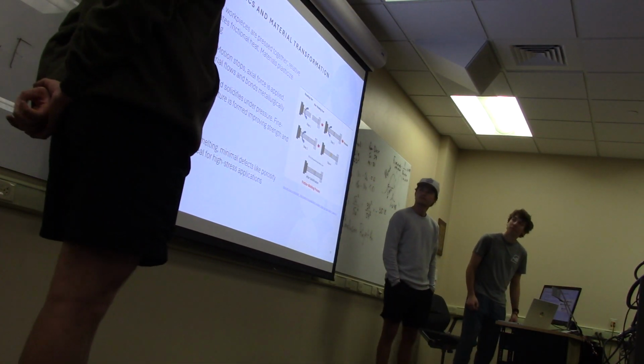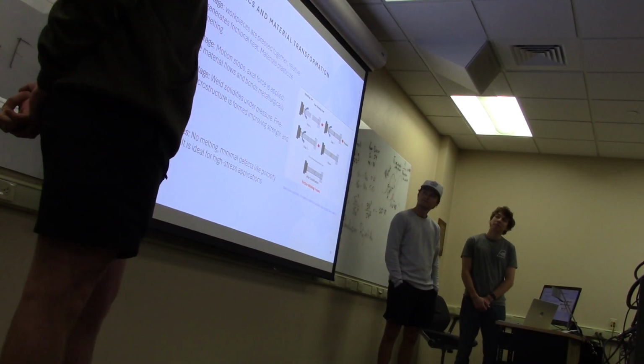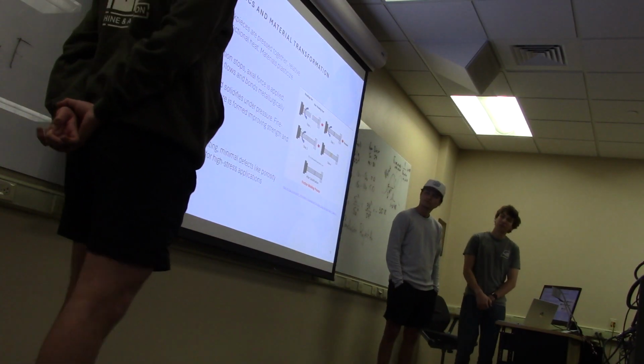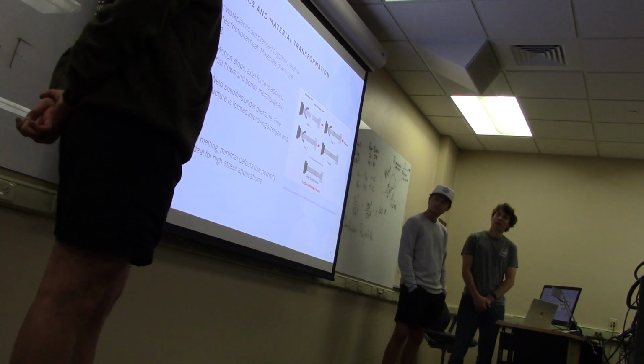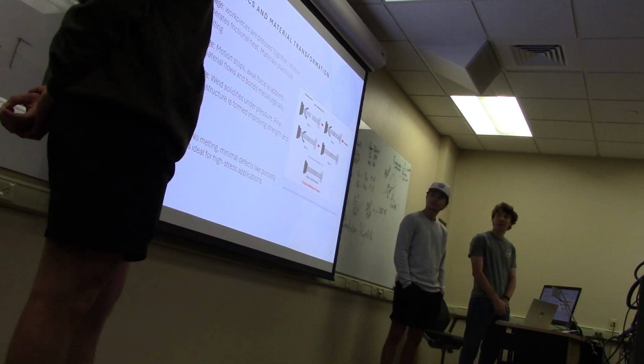So the first stage is the friction stage. Workpieces are pressed together, relative motion generates frictional heat, and the material is plasticized without melting. Then comes the forging stage, where motion stops and axial force is applied. The plasticized material then flows and bonds metallurgically. And then lastly, the cooling stage, where the weld solidifies under pressure.